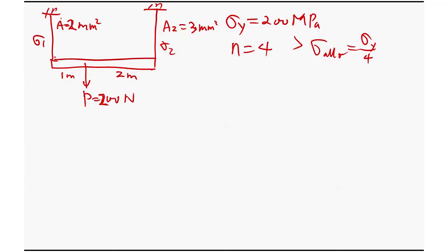You make a cut there. The reason I'm making the cut there is I need to find the force inside. Okay, so we make the cut. That's the rationale. Why don't I make a cut here? That's the rationale. Okay, so I make 2 cuts here. Once you make a cut, this is your free body. So you have a P here, then you have this part of the cable, and then this is the N1. And this is the second part of the cable,